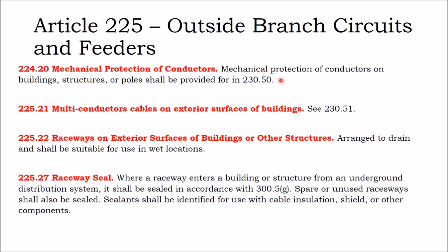And when you go inside the building, you still need mechanical protection. In fact, your mechanical protection gets even harsher. They say you need to be in metal conduit, so metal providing a little bit more protection than PVC. And you can be in PVC up on the rooftop. You can't be in PVC with at least DC wiring inside the roof.